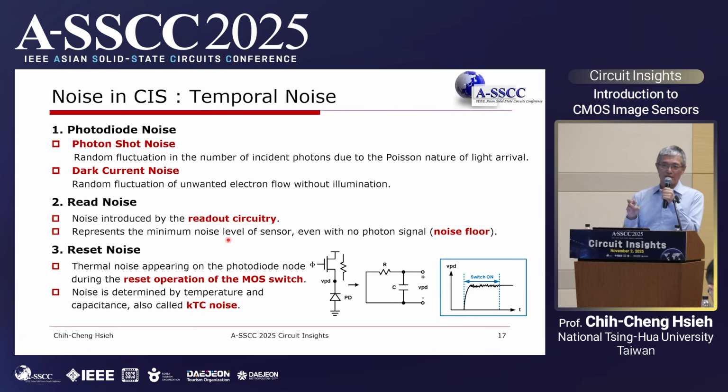And I think you may know that every amplification can reduce the input-referred noise from the following circuit, right? So we try to implement front-stage gain and try to reduce the input-referred noise from the following circuit, for example, the quantization of the ADC.